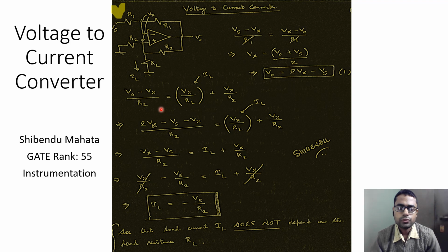So this is more or less it. There would be, at a higher semester, a lot of modifications to this circuit, considering the fact that all these resistances would have their own tolerances. That means even if we write these to be R1 and R1, in practice you will find that these are never matched resistors. And so there will be some variations. So this could be R1 plus some delta R and this could be R1 minus delta R, or within those tolerance limits. And so it becomes slightly more complicated. The operational amplifier is definitely not an ideal one. And so one can also consider these non-idealities and try to obtain an expression for V0.